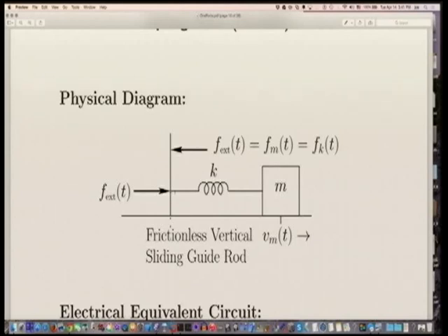And so what does it see? It sees a spring terminated by a mass. And so we talked about parallel and series. So the spring compression force is exactly the same force that's driving the mass. So that's a parallel connection, common force. So the port is described completely by impedance Ms for the mass in parallel with impedance k over s.